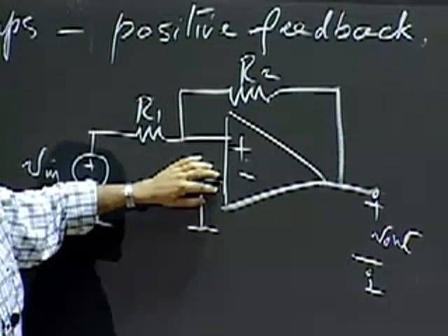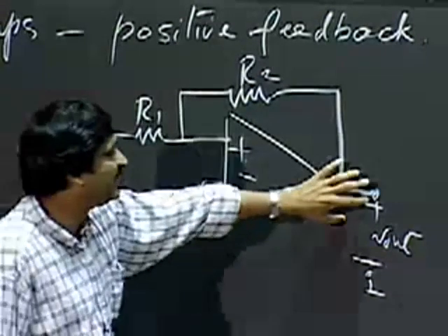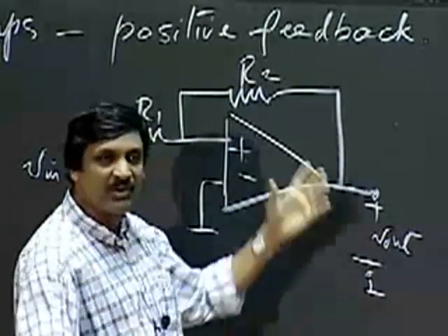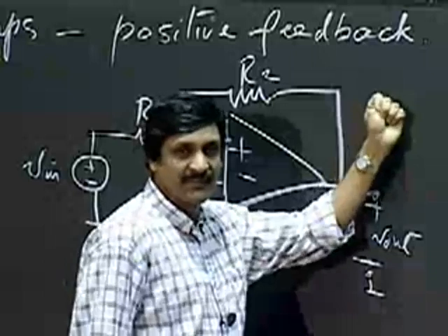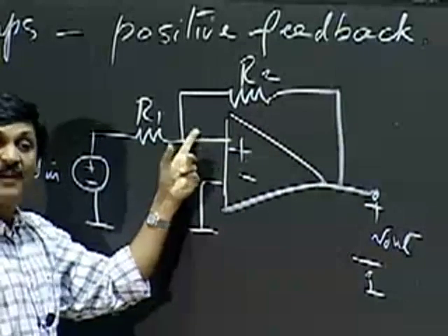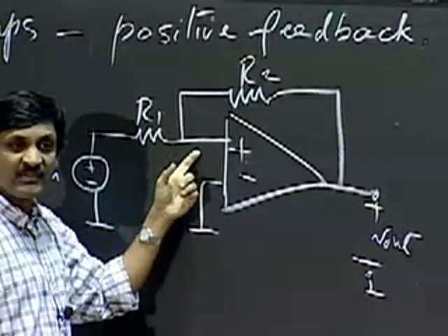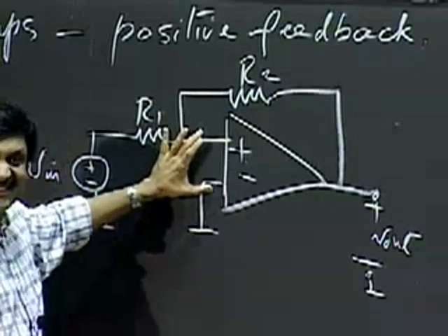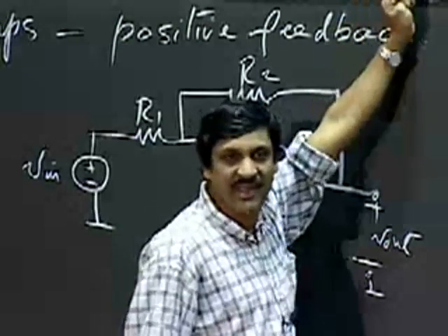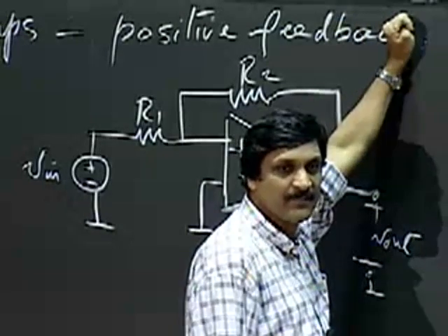If this is 0, okay, let's say for example that this output tends to go a little bit more positive. Okay, this output due to some noise or perturbation tends to go up a little bit. If that goes up a little bit, then because of feedback, this node tends to go up a little bit. If this node tends to go up a little bit, this exacerbates the positive input here, and this one goes ka-chunk, whacks into the positive rail.